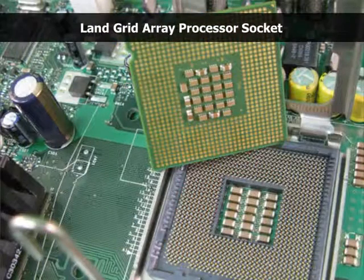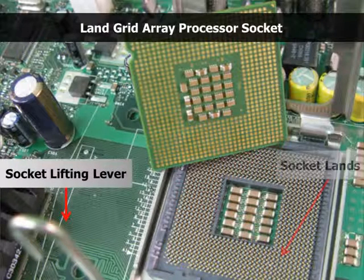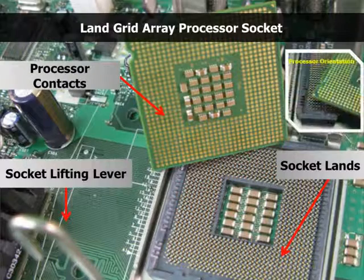Next, you have what's called the land grid array. If you actually look at the processor here, it does not have pins. It actually has metallic surfaces that then align to the socket underneath. So there are no pins, so the pins can't get bent. It's less susceptible to damage. And in fact, the computer that we'll be building throughout this particular course actually uses a land grid array processor socket. So you still have your socket lifting lever and the socket lands, as they're called, to actually interconnect to what's on the socket. And there's the contacts. Pretty much you can see how it lines up by the little picture off to the right-hand corner.